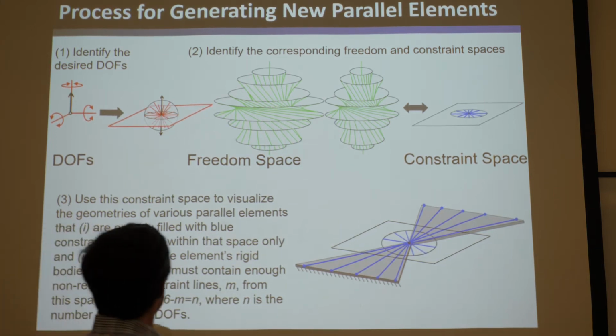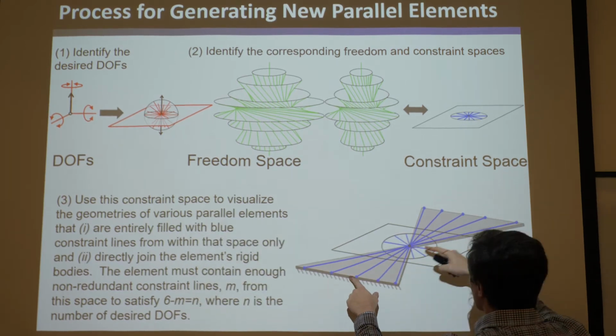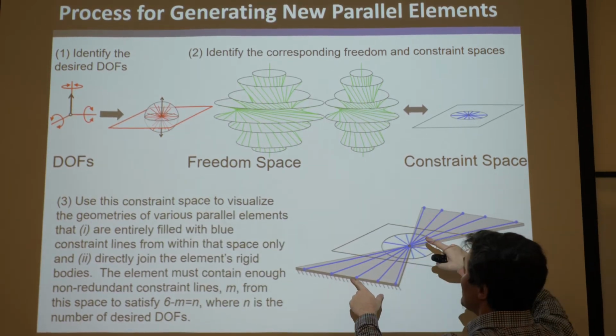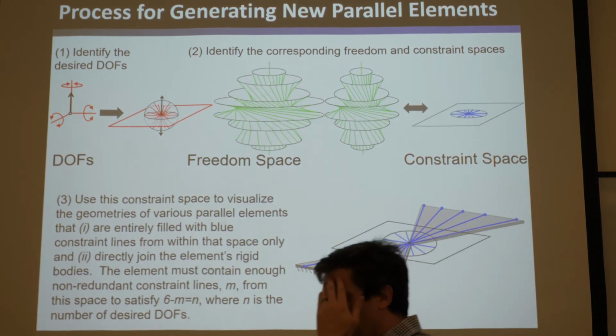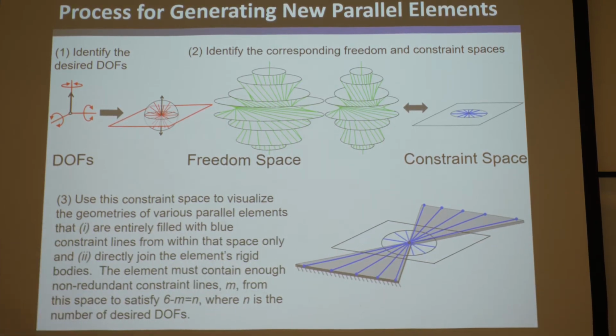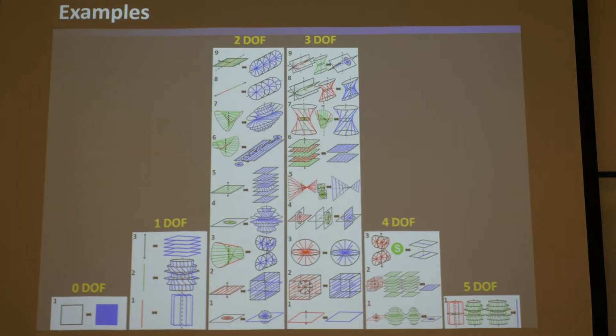Okay, so you could visualize that. Be a rotation up there, a rotation here, a rotation up there, and a translation, okay? And this would constrain all the other degrees of freedom. And it's indeed a parallel element, okay? And it's order of constraint of 2. So it's not over-constrained, it just has an order of constraint of 2. It counts as 2. Okay? So let's look at other interesting ones and thereby learn some tricks here.